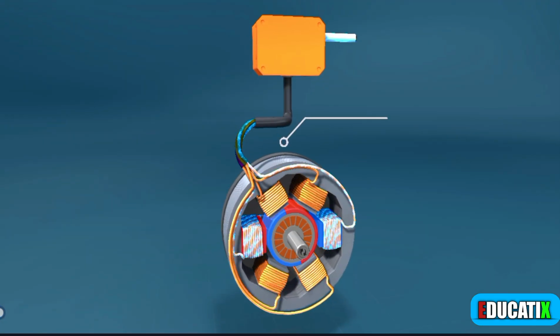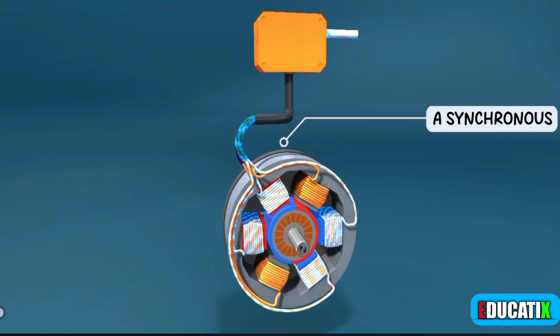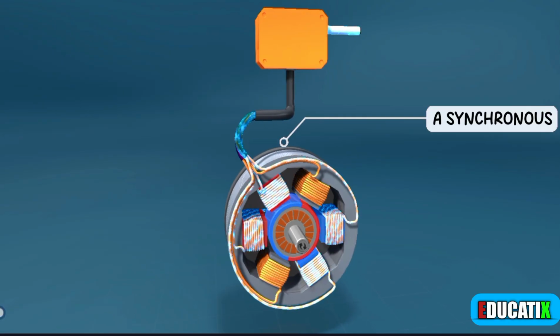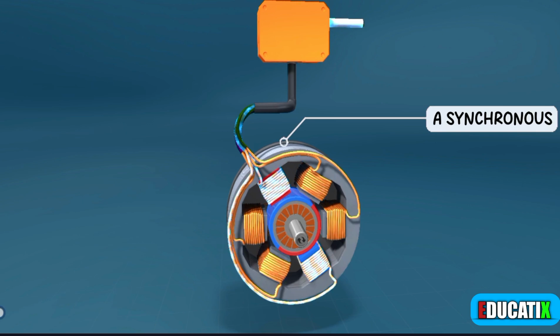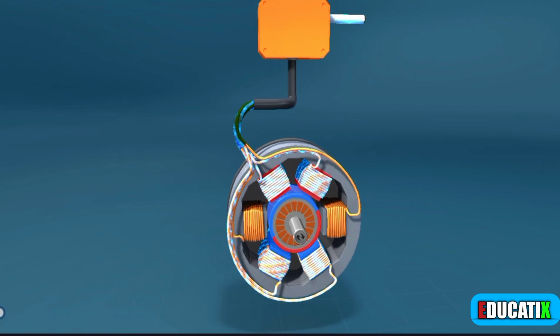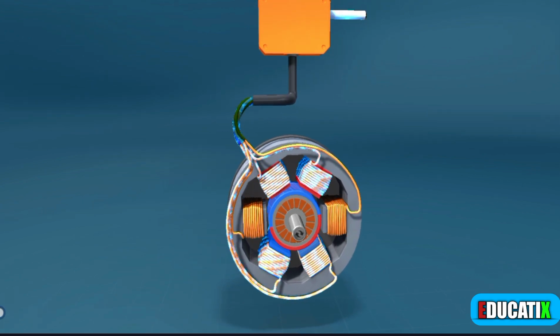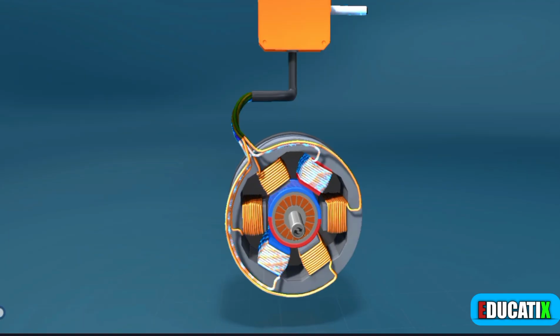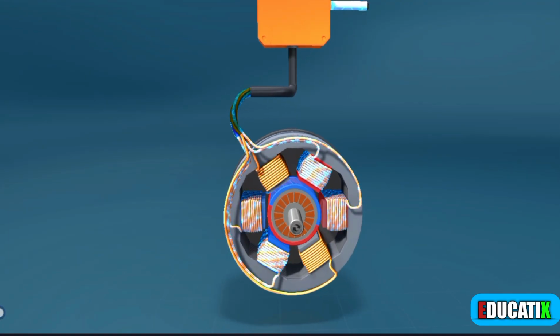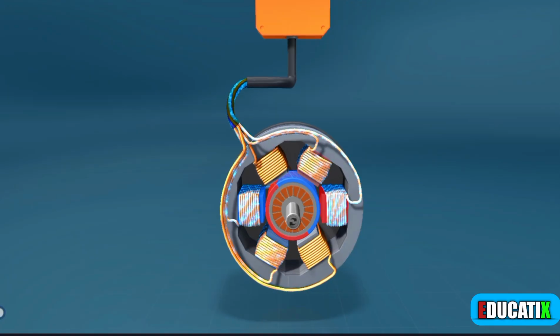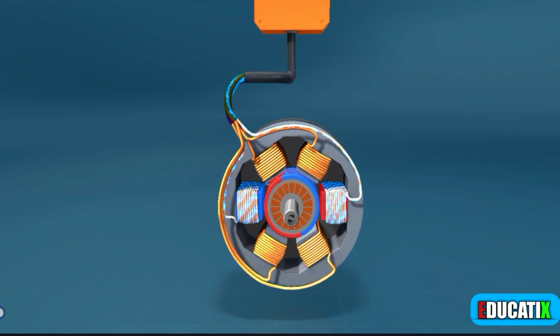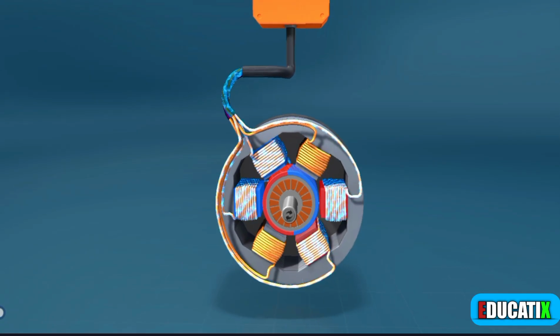The principle of operation of asynchronous motors is based on the phenomenon of induction. They also contain two fundamental parts, a stator and a rotor. The stator consists of several coils, to which an alternating current is applied. The rotor can be a simple metal cylinder, but it is usually a coil that does not receive current from outside. It will be induced in it.